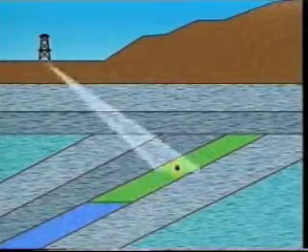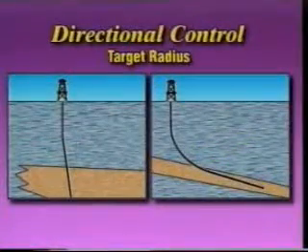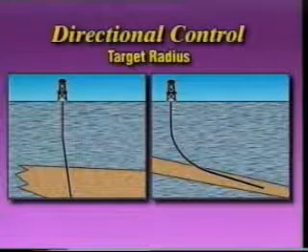Directional and non-directional wells have similar planning and equipment requirements, although, as we would expect, directional well planning involves additional considerations. The most basic of these is establishing a well trajectory or profile. Our goal in planning a well profile is to determine the most economic path from the surface to the bottom hole location. We first have to determine the target coordinates with respect to the proposed surface location.